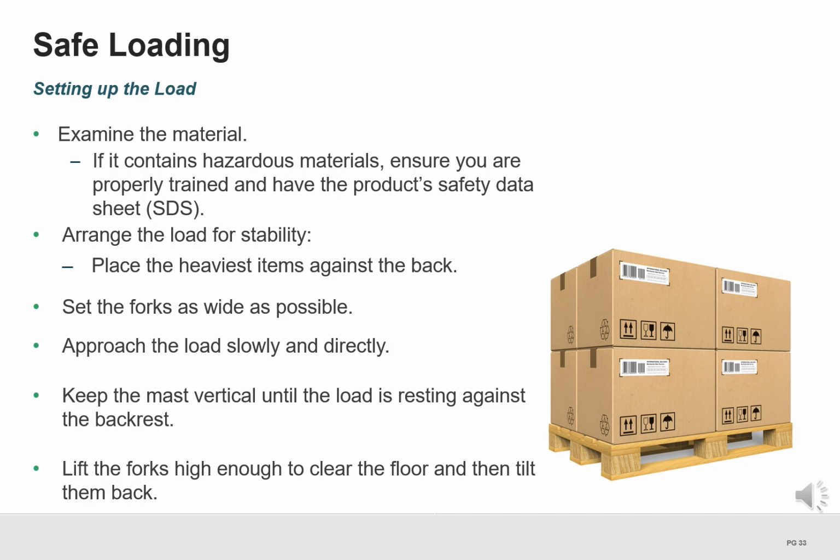Approach the load slowly and directly to maintain control. Keep the mast vertical until the load is fully seated against the backrest. Then lift the load just high enough to clear the floor and tilt it back to secure it.